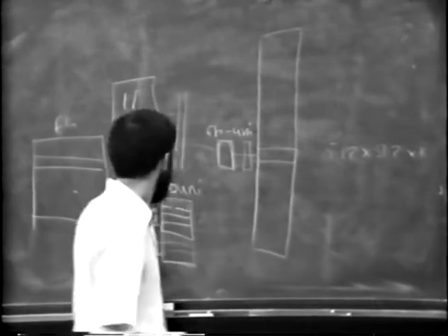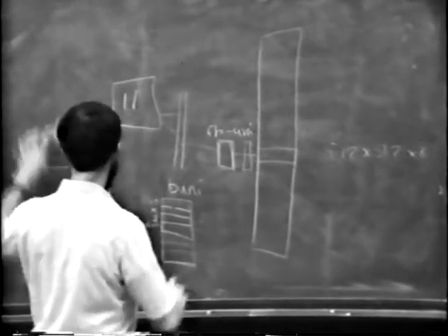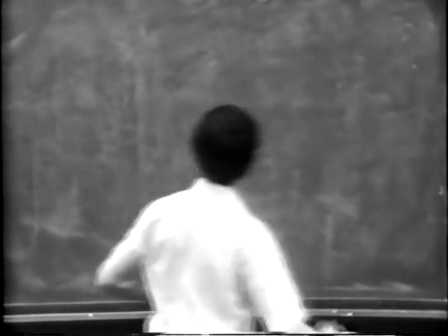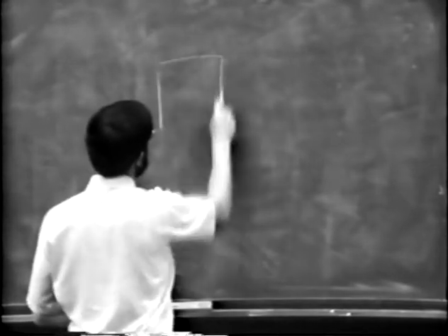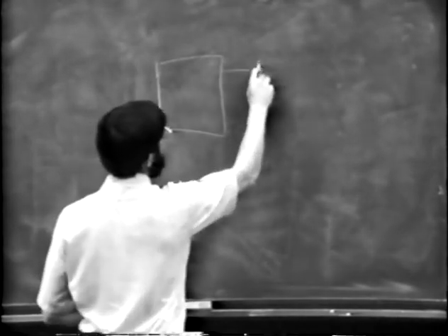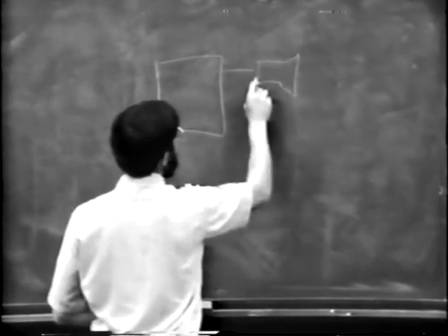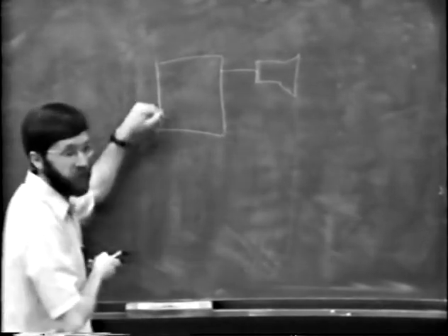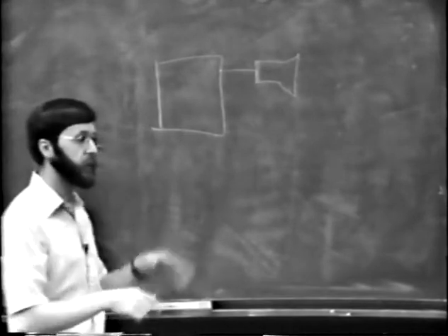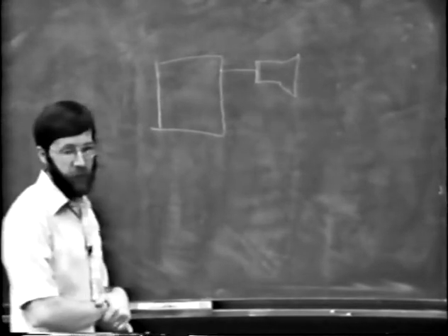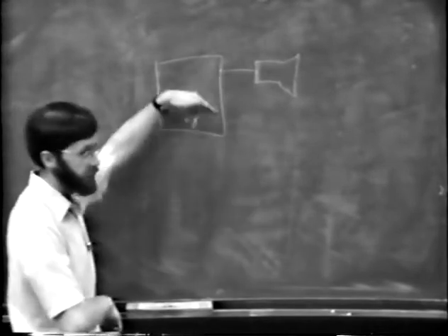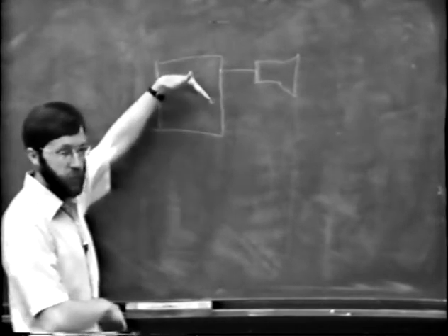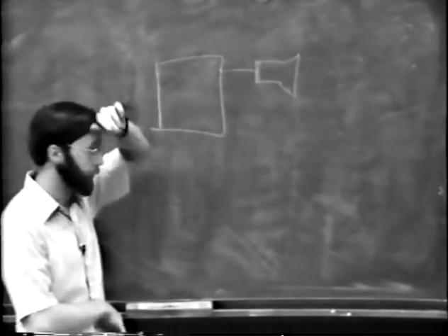All right, now, leaving the interfaces for a while, let's talk about the frame buffer itself, the display. We've got this memory with a video port coming out of it. I've seen frame buffers, still being made nowadays, where if you make some sudden change to the memory or you change modes, you can see a glitch in the picture. The better frame buffer manufacturers never have glitches in the pictures. This thing always refreshes. The worst you can do is turn it off, or change the parameters, but as you're changing data, you should never see anything in the picture.